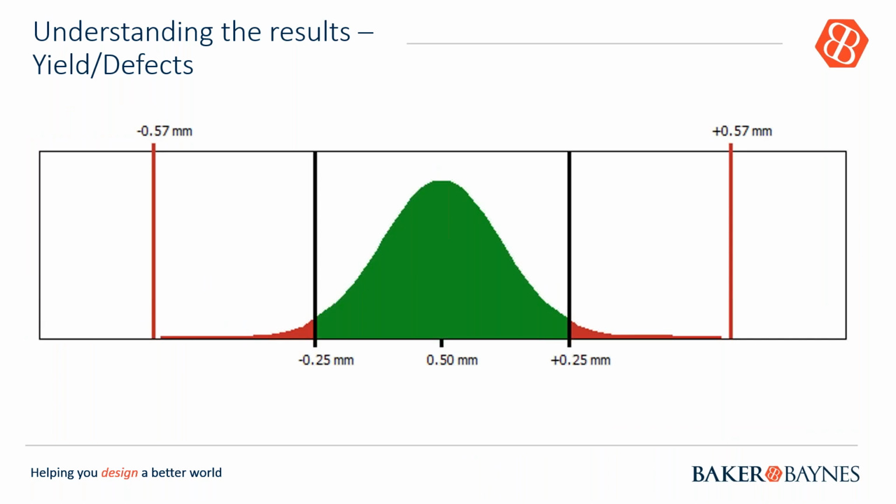So in here, all manufactured parts will be slightly different in size to the nominal dimension. If you measure every part and plot it on a graph, you would end up with a plot looking something like that, okay? So the bulge in the middle represents the average dimension of the component, clustered around the nominal dimension specified.